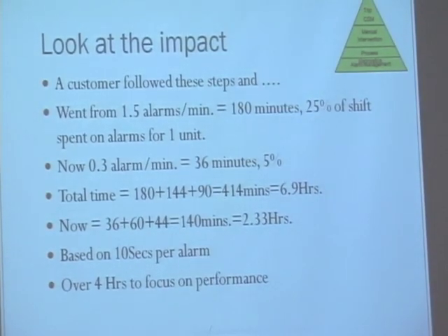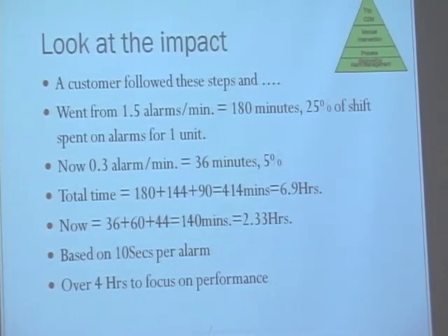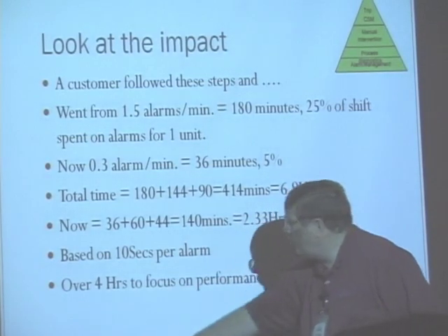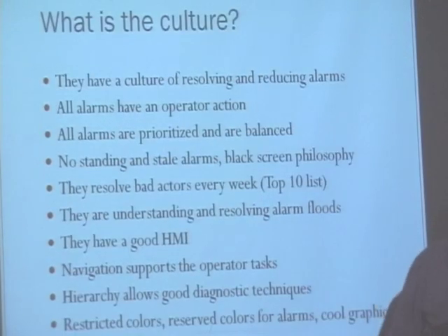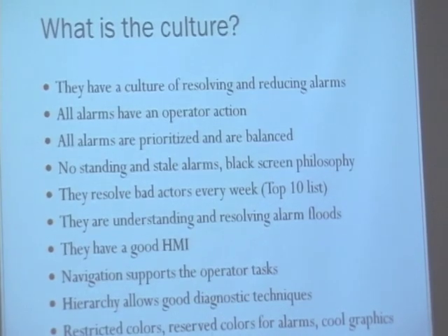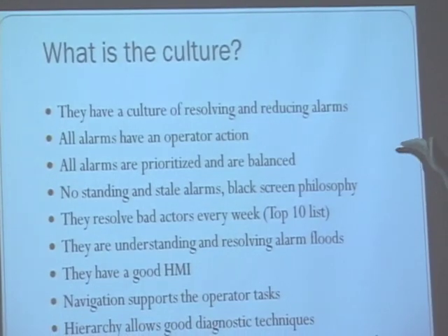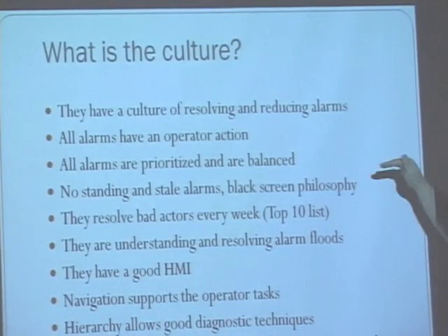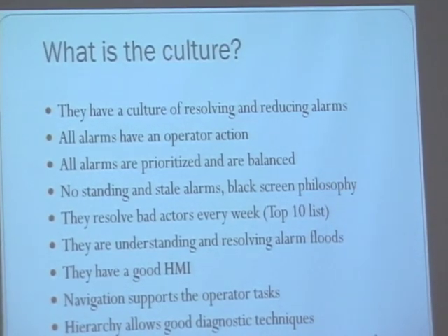And I'm sure the operator was spending more than 10 seconds on some of those alarms. So it just goes to show you we can actually create over 4 hours to focus now on performance rather than just addressing alarms. The culture that this company now has is a culture of resolving and reducing alarms. All alarms have an operator action. All alarms are prioritized and balanced between those priorities. They work against guidance about how many high priority alarms we should have, as against medium priority, as against low priority. Obviously, we've got to have a balance.